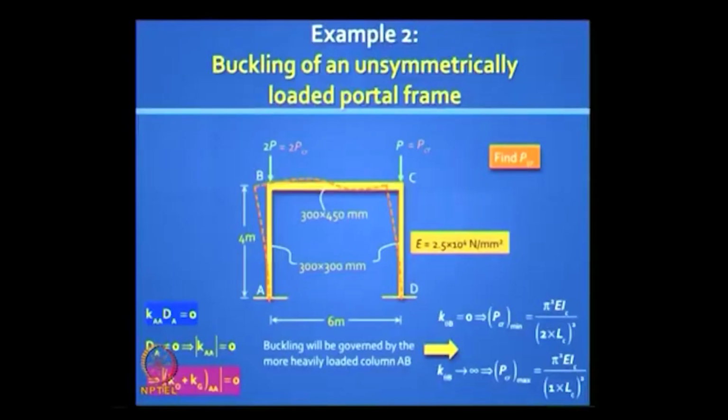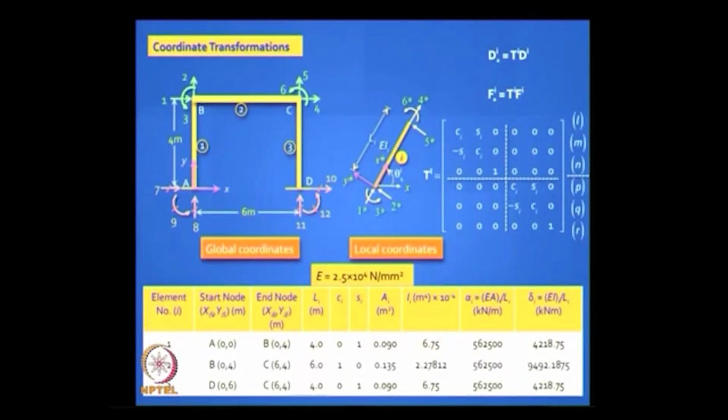Ke will be either 2 or 1, most likely it will be somewhere in between, you have to find out the value. Okay, so you must always as an engineer have an initial guess of what the likely load is. Okay, this is a slide I am picking up from what we did when we did portal frames without any P delta effect.